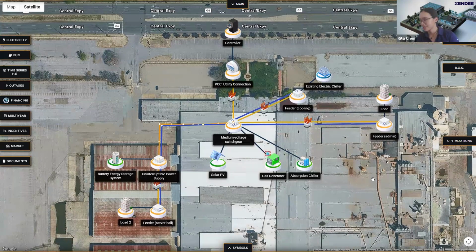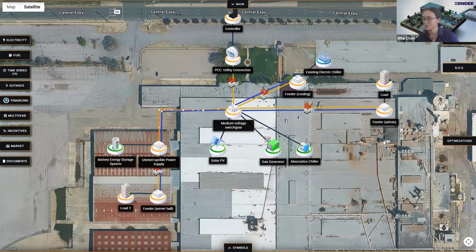All right, quick summary of what we did. We now have a complete, detailed multi-node model. We stepped down our voltage all the way from the utility to our switchgear to our endpoints used. And we also separated out where all the DERs and loads are going to be.